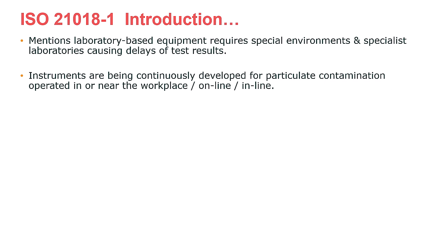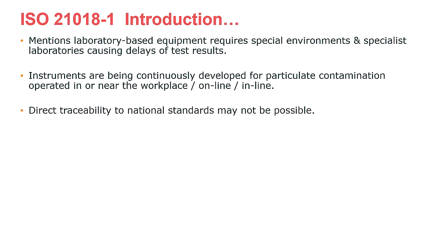It also talks about the fact that there are instruments that are being developed for particulate contamination monitoring that can be used near the workspace, which basically means in the field, online or inline. And it also mentions that the traceability standards, so ISO 11171, may not be a way to calibrate these new automated particle counters or contamination monitors.